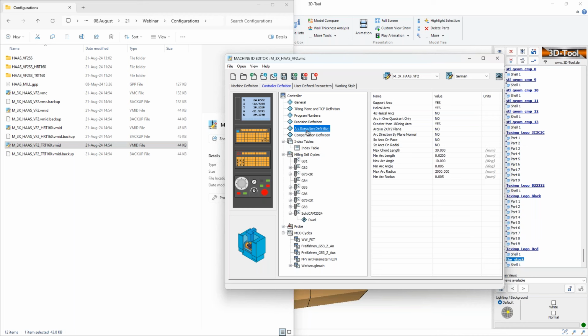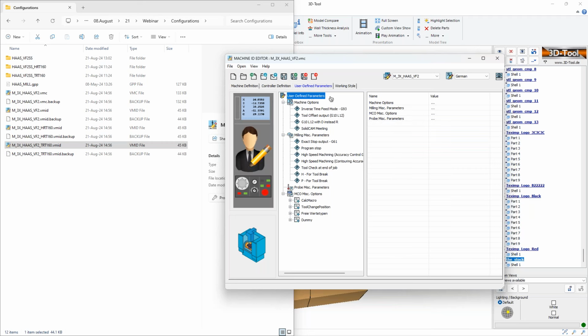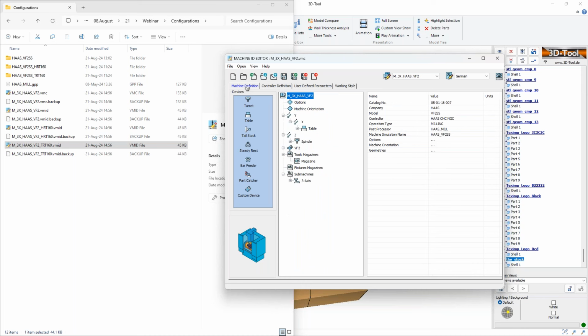The same feature is also available when we're talking about the parameters. So for instance, you discovered how 4-axis helical arcs works on the particular machine, and you want to apply these changes among all post-processors in this group. You'll just go to parameter, change it, right-click, apply to all configurations, and that's done. That's basically it. Of course, the last thing before we go to questions,